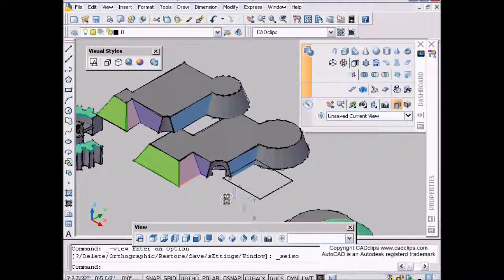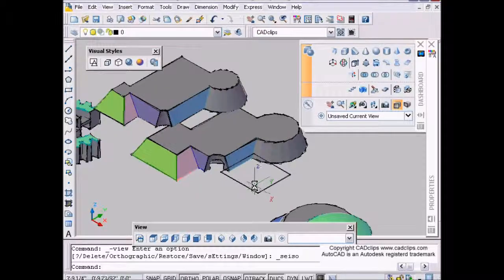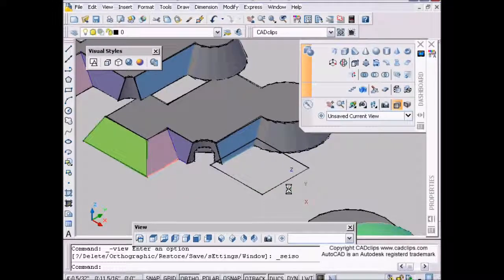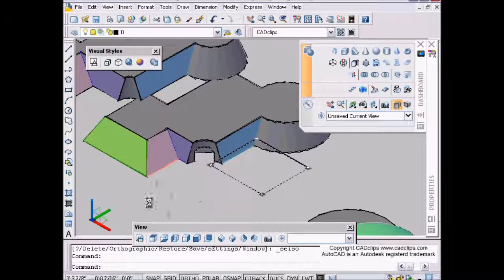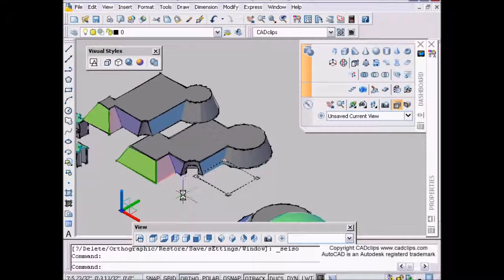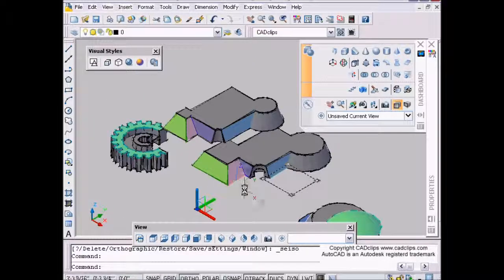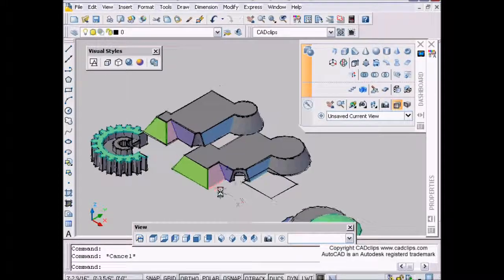The main thing is draw the object on one plane, switch to a perpendicular view, and move that plane up and down. And when you do the slice, I recommend resetting your UCS to the plane that the slicing plane was drawn on. So a couple little extra tips there. And once again, as a prerequisite, have a look at our previous 3D videos for AutoCAD 2000.